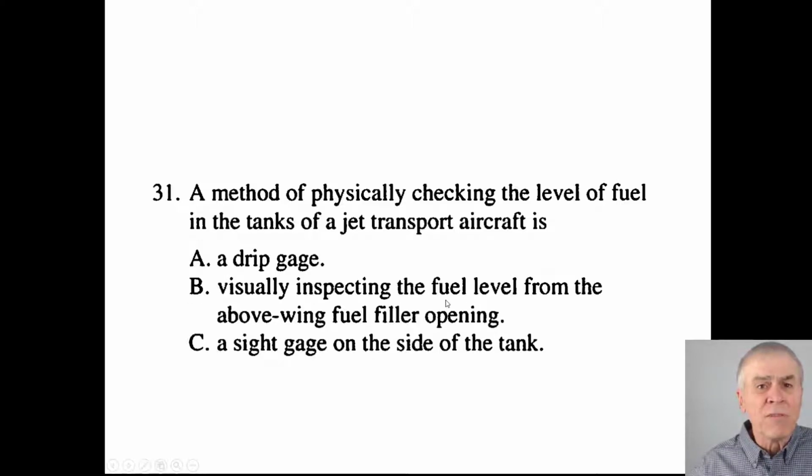B, by visually inspecting the fuel level from the above wing fuel filler openings. Well, a jet transport aircraft doesn't always have a filler opening above the wing. A lot of times it's below the wing, a pressure fueling. And you wouldn't do it that way anyway.